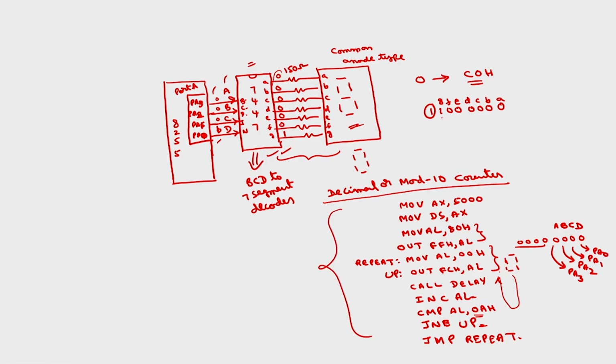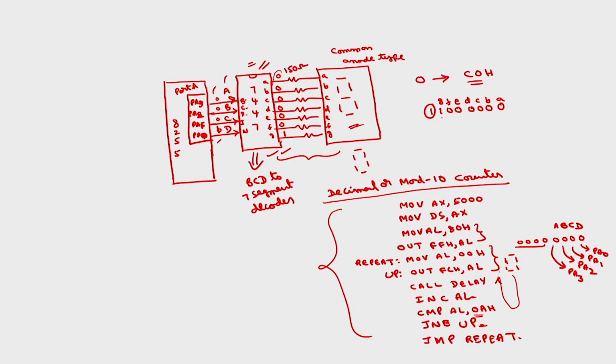If I want to connect multiple 7 segment displays, suppose I want to connect 8 7 segment displays, then we have to use 8 7447s, if I want to directly use them. So for interfacing eight 7 segment displays, we have to use 8 7447 ICs.